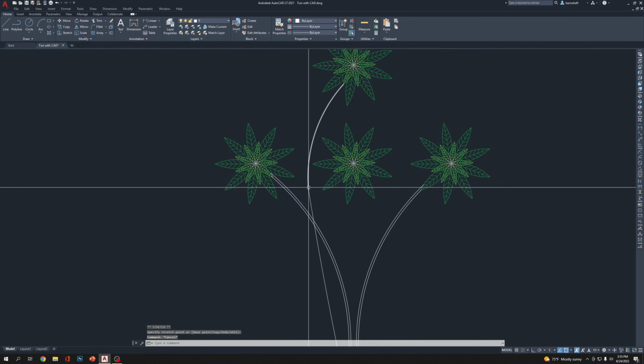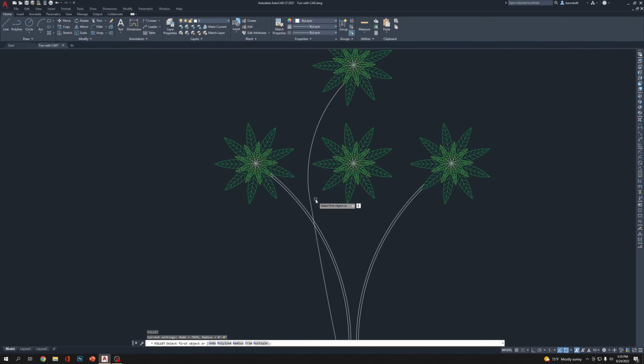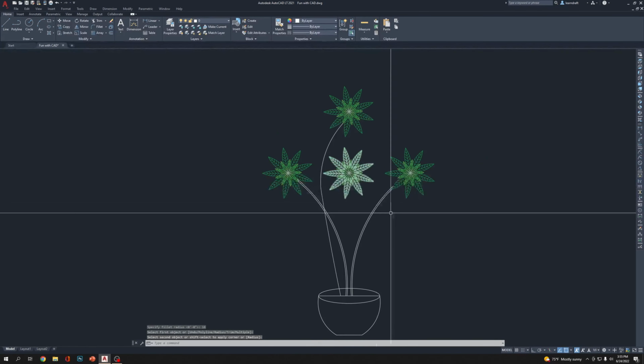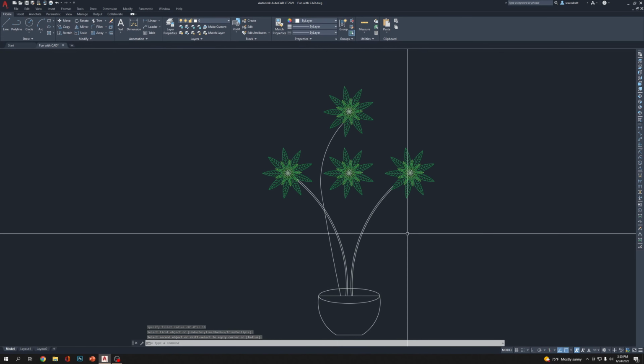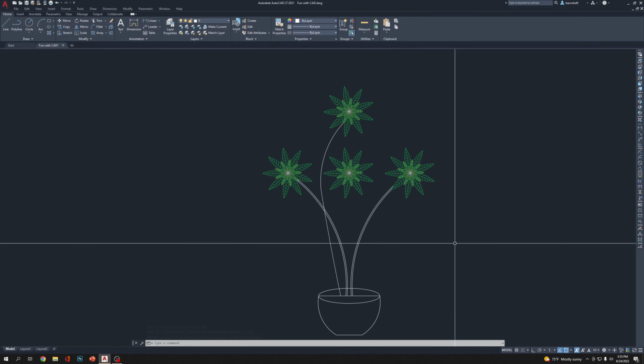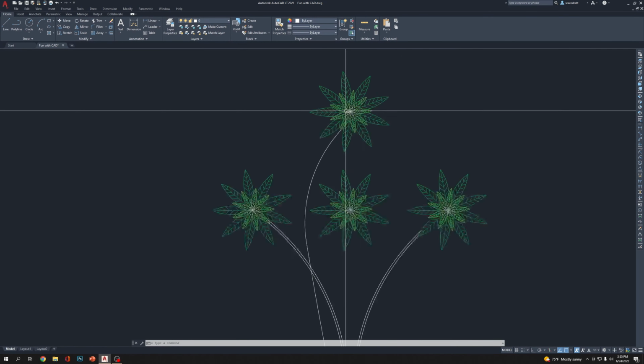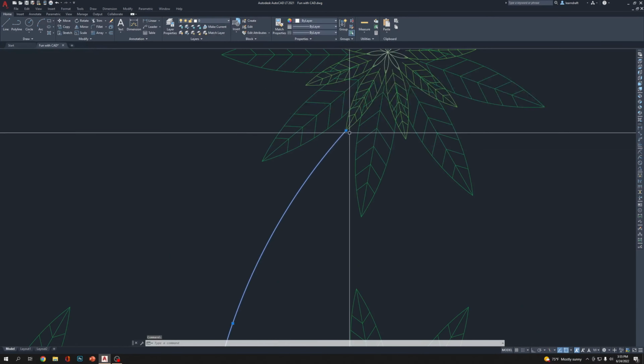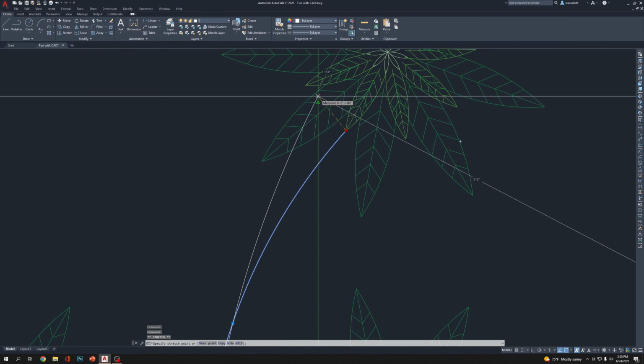Okay, let's make a fillet here. So fillet, enter, radius, enter, make it 18 inches. Let's see how it looks. Oopsie. Okay, now poly editing becomes a little more good. No. Instead of this one, go to this line. If I pull this one up a little bit, maybe it looks better.